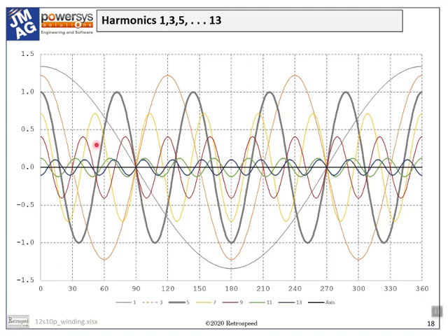Another important effect of the winding harmonics is that they contribute to the so-called harmonic leakage inductance, which increases the overall inductance of the phase windings. And that has been very important in the 12-slot 10-pole motor, particularly in relation to high-speed operation where field weakening, or flux weakening, requires higher inductance.